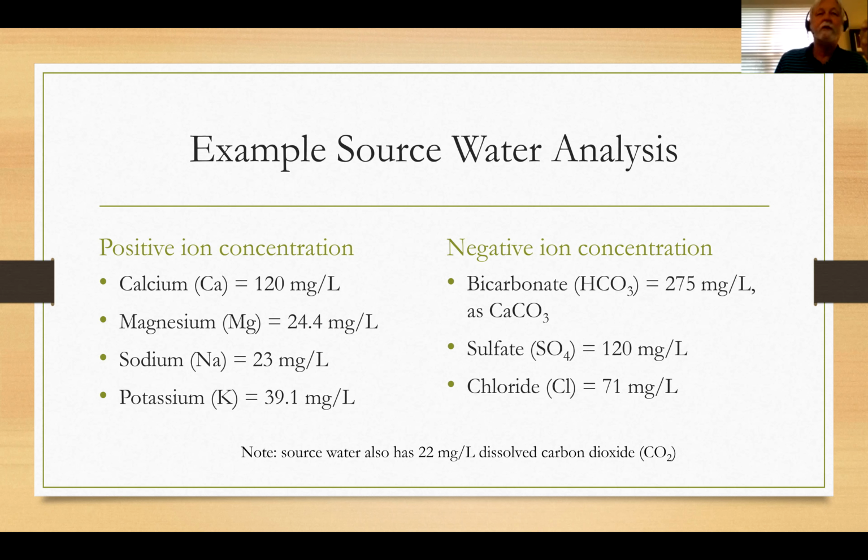So calcium first, magnesium second, sodium, potassium, any other cations that we want to include because they're of significant concentration. I want to do this because, first of all, calcium and magnesium are in fact hardness. Sodium and potassium are monovalent. They are not hardness. Hardness is divalent cations. And almost always it's pretty much calcium and magnesium.